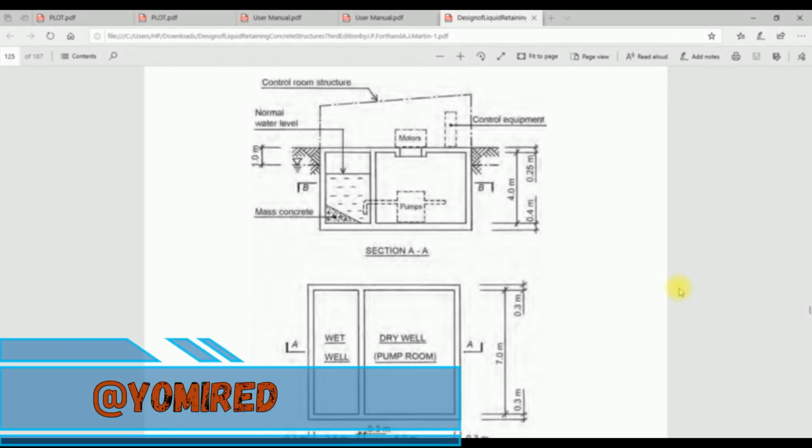Good day. We'll be designing the water retaining structures and this tank, which is an anchor. We check for the uplift by checking the dead load of each and every one against the soil pressure and making sure that the tightness class is 3, which means no leakage permitted.